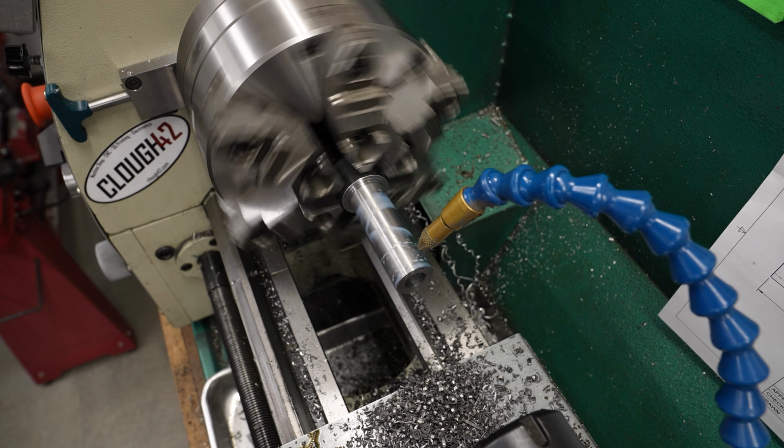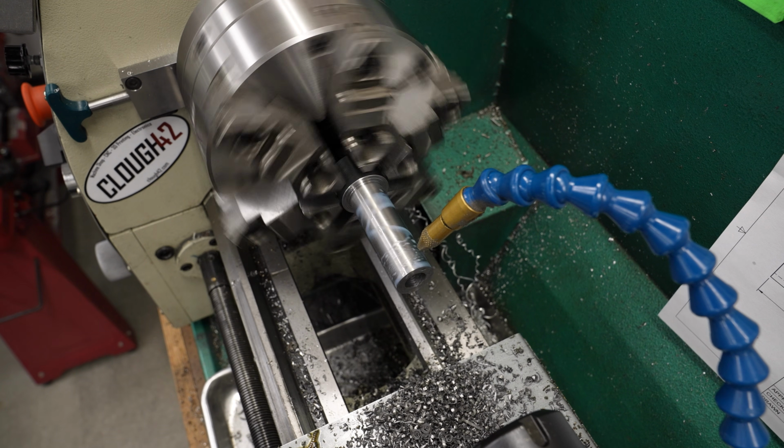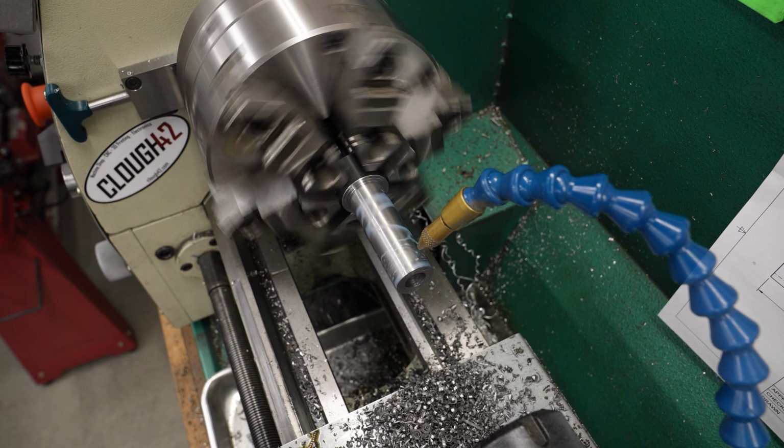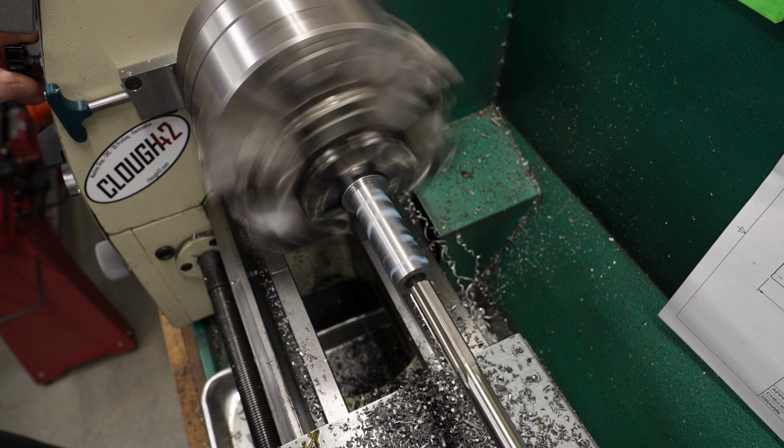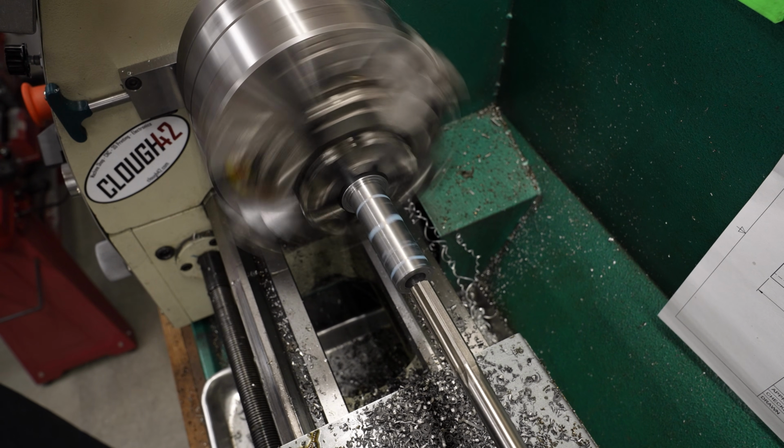because it got quite hot from all of those operations. And once we get it down to room temperature or even a little bit colder than room temperature, we can bring it to the final size. Now for the bore, I actually have a 12 millimeter reamer, so this is what I'm going to use.